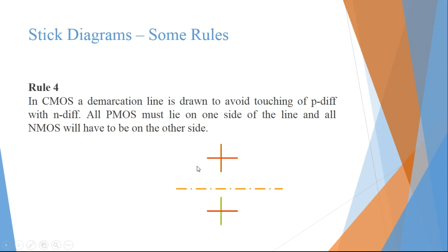And if we have more components, like more PMOS, suppose in the case of an AND, we have two transistors, right, two inputs. So we have more PMOS here. Then that PMOS should come near to this one on the top side. And in the bottom, another NMOS should be there, right? And in that particular way, the connection should be made, right?